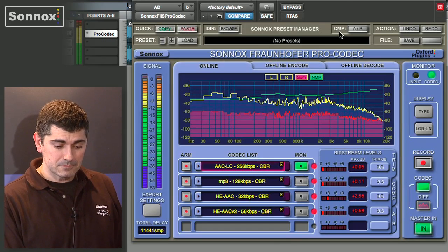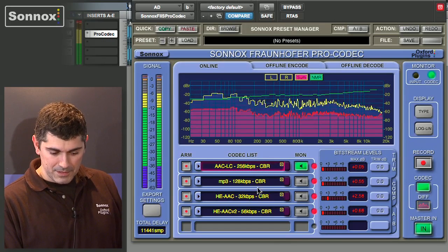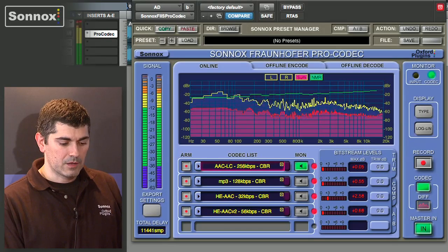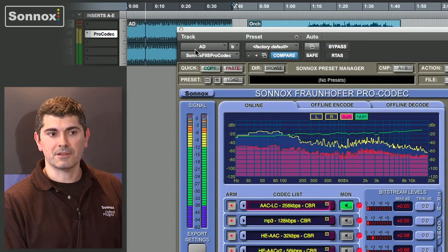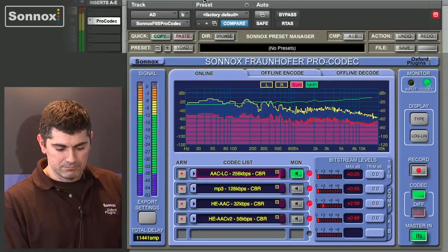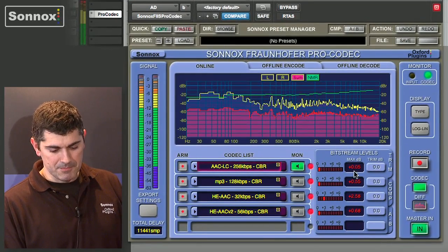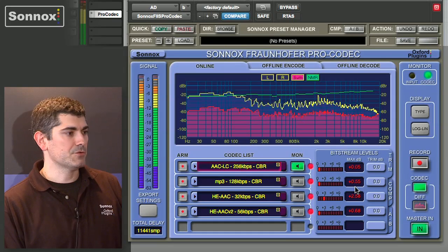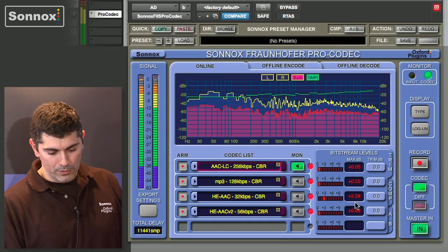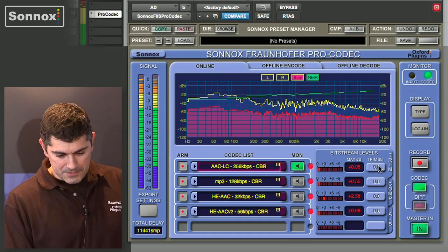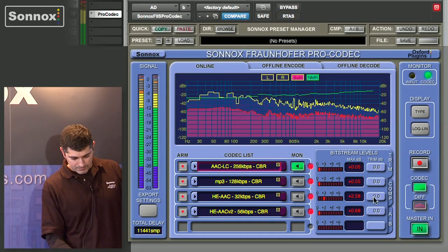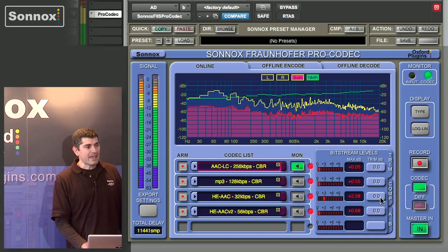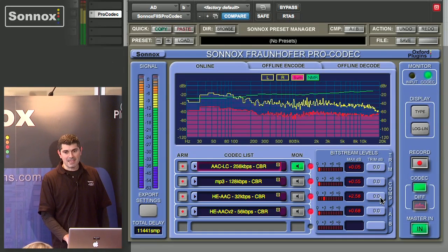That may happen depending on bit rates, but also depending on the signal level, which is in this case quite hot, I must say. So it will point out the maximum peak reached during playback, but not only that, it will give me the tools to compensate this amount with a gain reduction stage at the input.